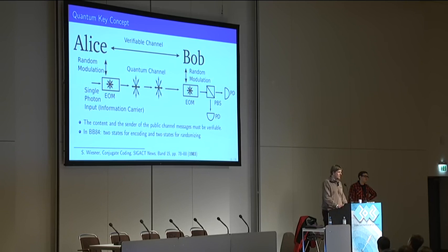And when it's of another polarization, it goes to the photodiode on the other side. But if you use a photodiode, you never have actually one single photon detection. With an avalanche photodiode, you can only detect a bunch of photons coming to the diode. You're not able to detect one single photon because this will not cause the avalanche effect.